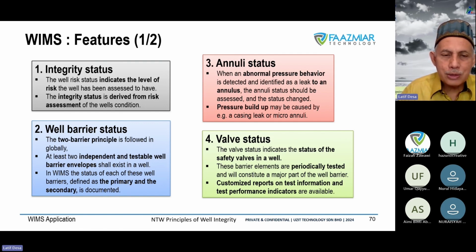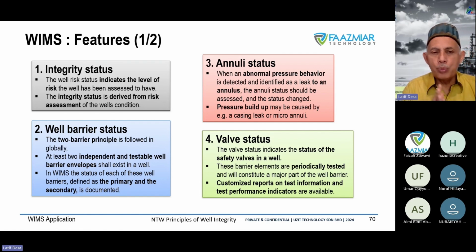The valve status: the valves become key components of the wetted material, wetted by the hydrocarbon flow. We know that the valve itself is exposed to a harsh environment. You have the hydrocarbon, we can have CO2, we have H2S that can attack the valve very quickly. Because the valve comes to surface, it's at the facilities on the platform itself, that's why the valve is exposed. So there must be a proper maintenance check, and understanding about what the specs for the valve are.